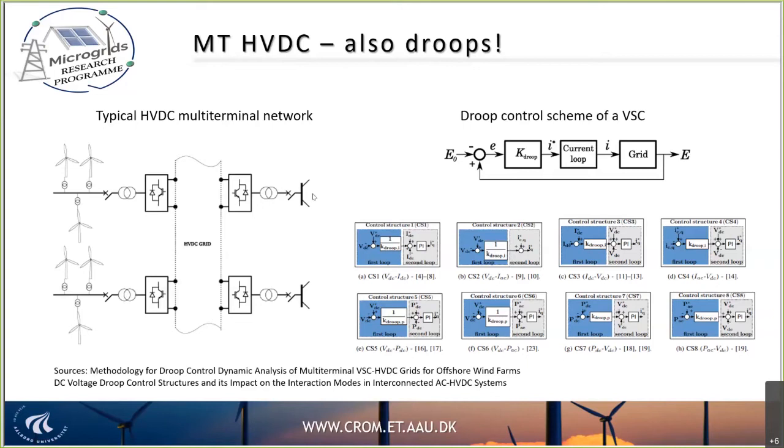There are many ways to implement a Droop control for these VSCs that make up the HVDC system, like using, for instance, voltage and current loops, or voltage loops without integrators. So you just droop it down, using sometimes current or sometimes power instead. But finally, all these concepts come down to voltage versus current or power droop. So this is basically the control that we can see nowadays that is massively applied.